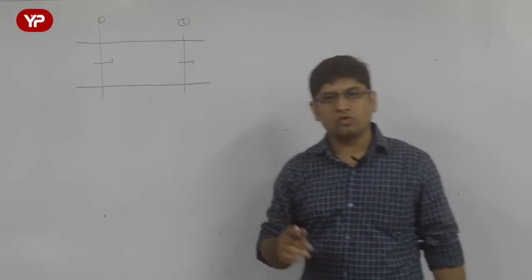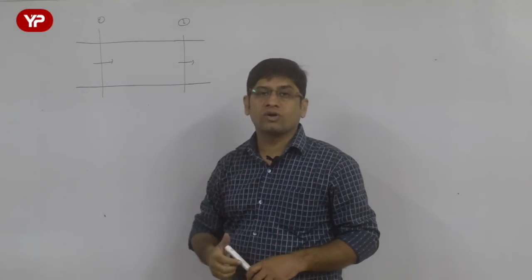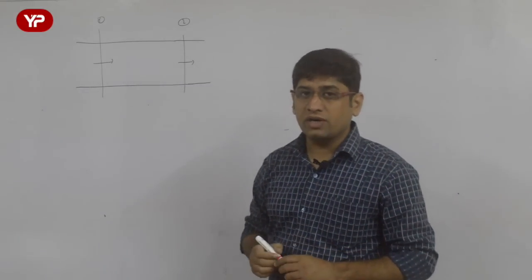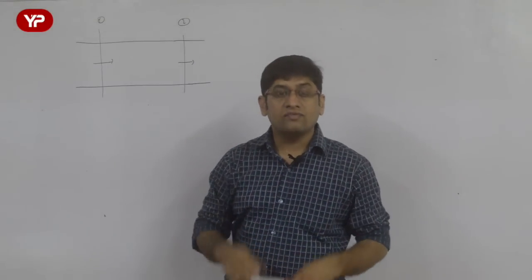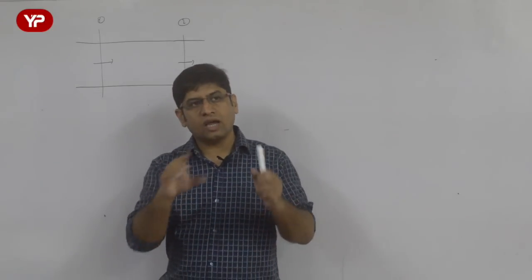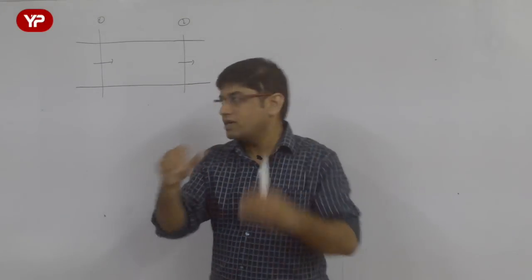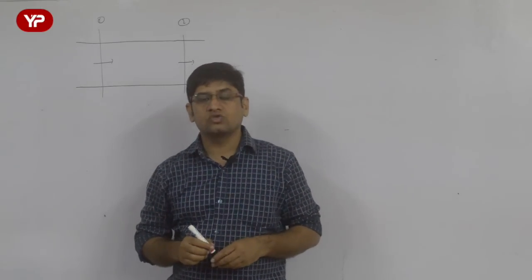Choice is yours. Number two, whenever you calculate various terms in the Bernoulli equation, these terms are calculated along a particular streamline. He is going to ask you that question also in the interview, where you are calculating P1, V1, Z1. So you say, sir, I am taking one streamline, preferably in the center, and I am going to write the Bernoulli equation at these 2 points.